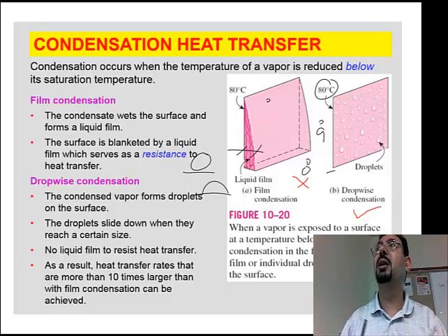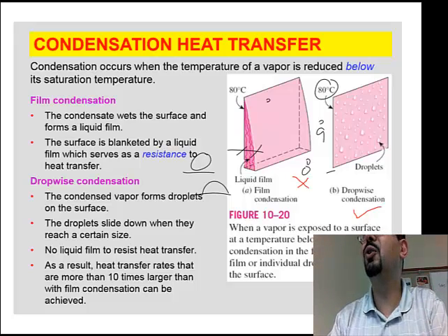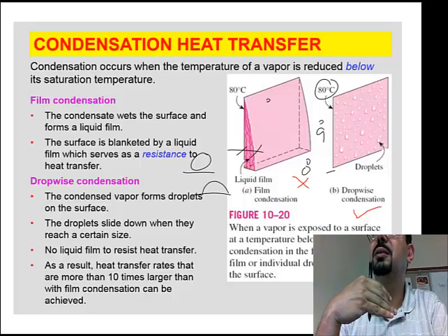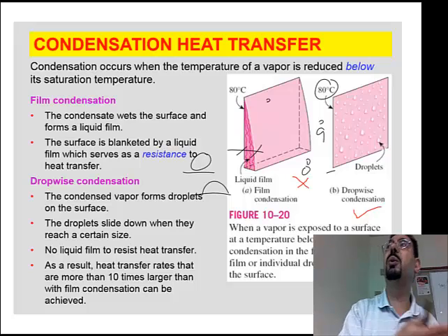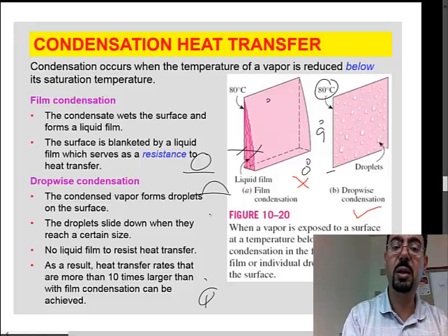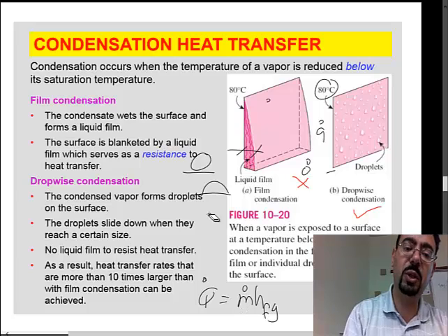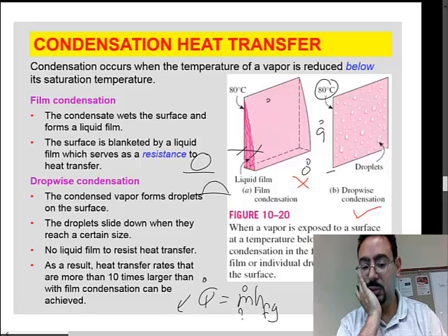There is HFG that we are using in reverse this time. We are not boiling it. No, we are condensing it. So we don't need the wall to give us the HFG. We are actually going to give the wall the HFG. But still, the equation is Q dot is m dot HFG. All right, and so to get the m dot, which is what's actually unknown, I need the Q. How am I going to get my Q?